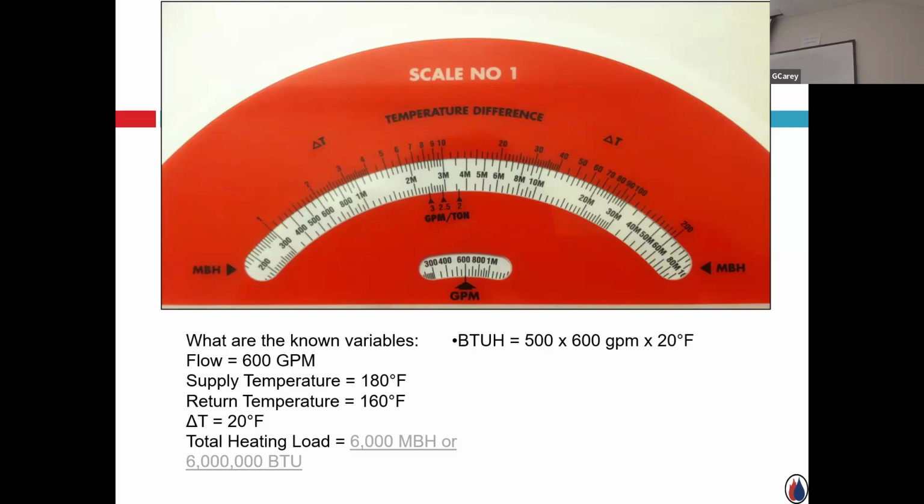You would have a chart, triple duty. Correct. What the degree opening of that. Correct. That's exactly right. You would need that information. Some of the newer stuff, much smaller in flow rates, will actually come with digital readouts. But that older stuff and the larger stuff, you're looking at pressure differential with the degree opening and putting that on a chart or a wheel and saying, okay, what is this telling me? And doing that is how we determine the 600. Correct.